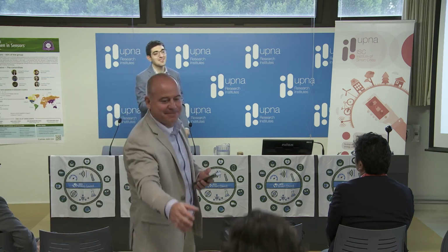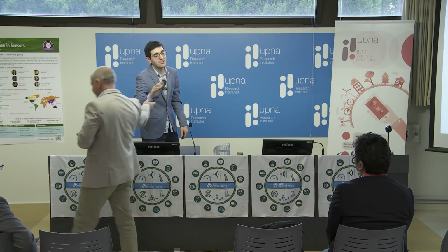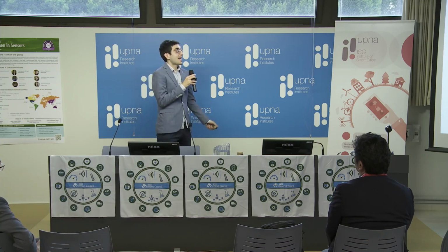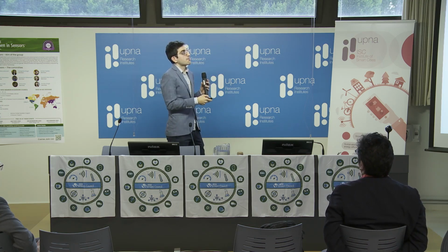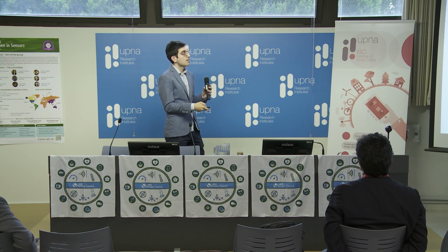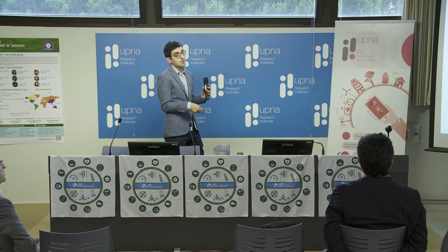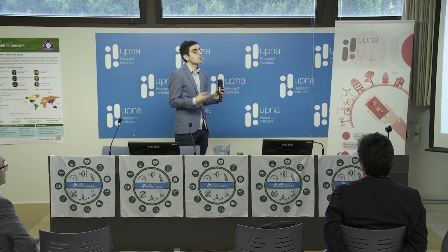Many things could go wrong. Thanks for the question. Right now, many things could go wrong because we are already trying to manufacture things, and for example, something important is that the sidewalls are vertical. My main limitation now is to see, for example, if I use a grating coupler, this would be the minimum feature size, which, like I have said, would be the grating period multiplied by the duty cycle. So I have to know whether the systems we are going to use are going to be able to reach that minimum feature size or not. For the moment, we are still working on that.